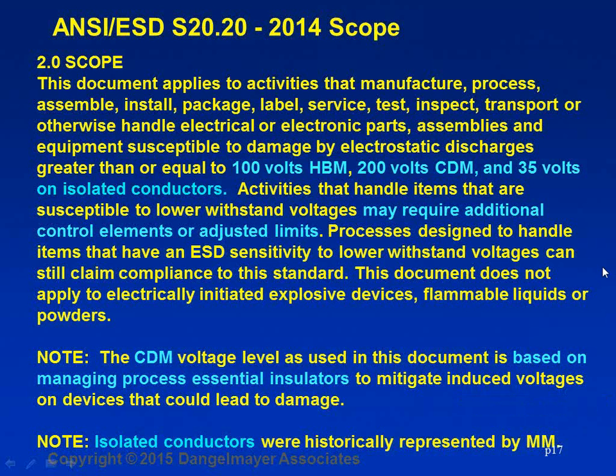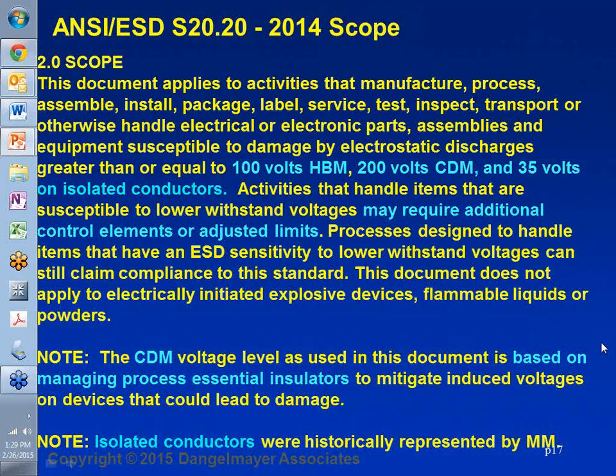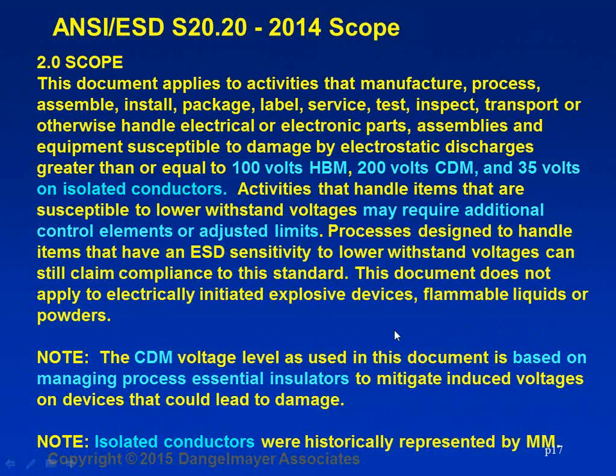I think, in general, smocks are a good thing. They provide a lot of continuity for what the process appears like when people are walking through it. I think it's the opinion of our organization, the Engelmeyer Associates, that garments don't provide a whole lot of protection from an ESD standpoint. And so therefore, whether they're rolled up or rolled down is irrelevant. Do you agree with that, Ted? Anybody else want to disagree with me?